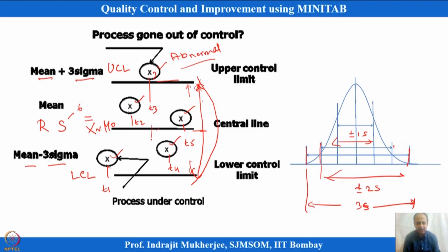So, whenever this goes outside the limit line, immediately a signal is given in the process, and an alarm will ring immediately, so that people understand. The operator will understand that something has gone wrong at this time point, some setting condition has abruptly changed, or maybe the input condition has abruptly changed. So, immediately I will look for assignable cause.